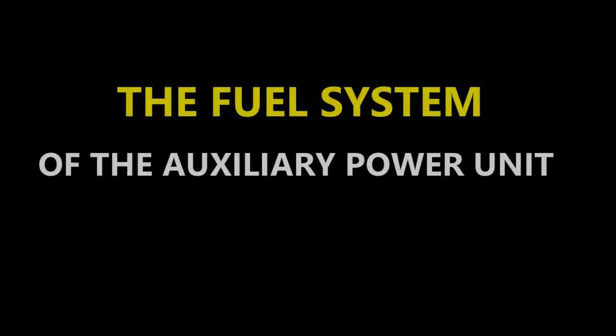Okay. All right. Now, what makes up the fuel system? Okay, I just said it's fully automatic. We have a couple of pressure switches. Obviously, something has to get from point A to point B, namely fuel. But we also have fuel filters. We also have a torque motor. You've got a shut-off solenoid as part of the fuel system components. You also have two manifolds. You have a primary and secondary fuel manifold. You also have the injector nozzle and your flow divider.